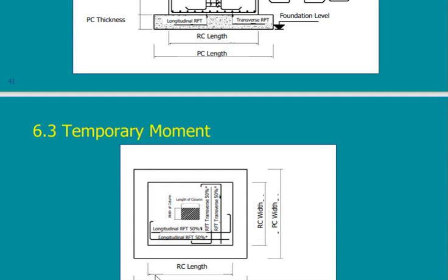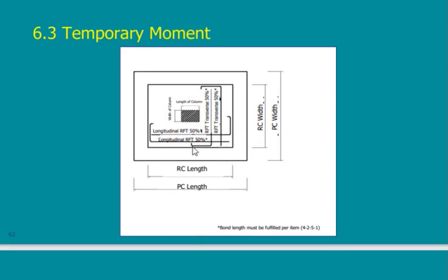In this case, also we use this. Instead of using a U-shape, I can use it with one side only, and the other one will have the side, the opposite side. Here I have this side, the next one will be with the side here. So in this case, I reduce this. Here I have a side, here I don't have a side. So I reduce one side of each rebar.